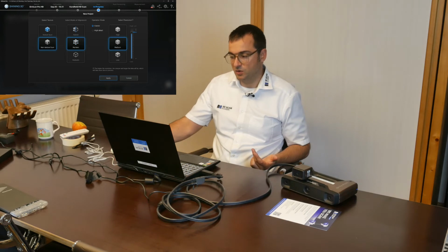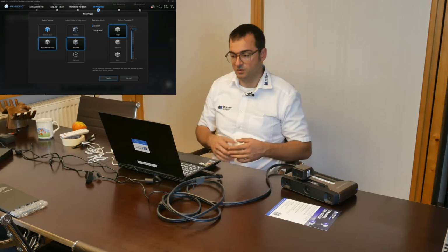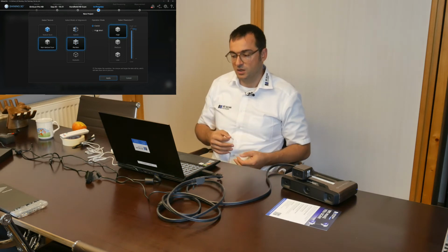in the HD mode. That means just going up here, not just to 0.25. It is possible here to go up to 0.2. Classic and high detail in this case is a filter that you will apply. That means high detail will not absorb so much the sharp edges in some structures. It will as well lead to a bit more sensitive result.